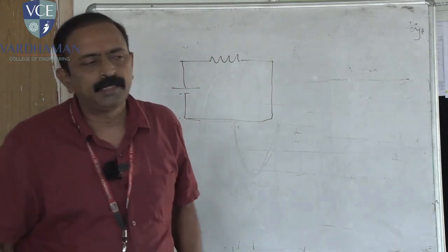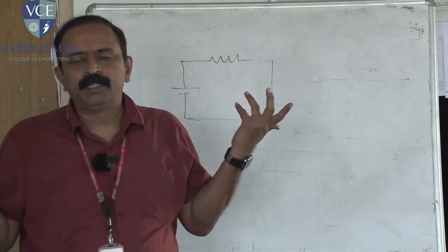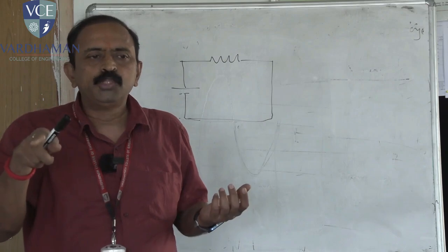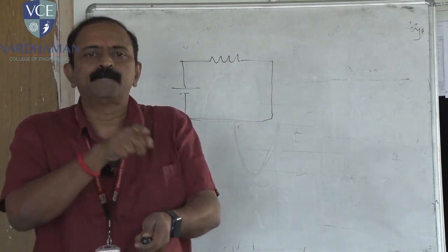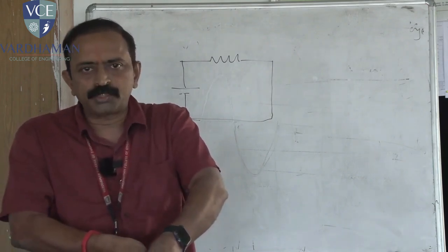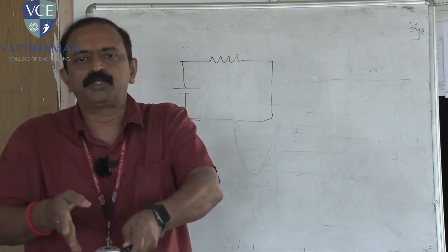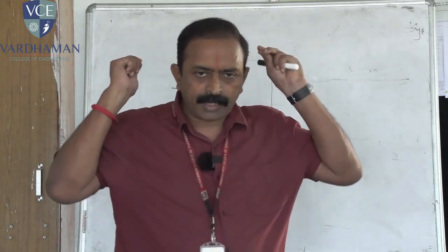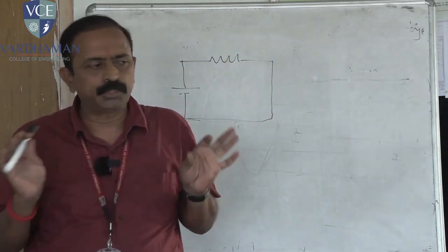And everyone should wear leather shoes. And one more important thing is, girls will come with loose hair. It is very dangerous while working with rotating devices. You need to bend towards the motor and take the speed of the motor while it is rotating, with an instrument called a tachometer. You have to insert the tachometer into the shaft of the rotating device. While doing that, if hair falls on the rotating device, it is dangerous for you. So I will ask all the girls, tie your hair tightly, keep it inside your apron, and come to this laboratory, particularly in this lab.